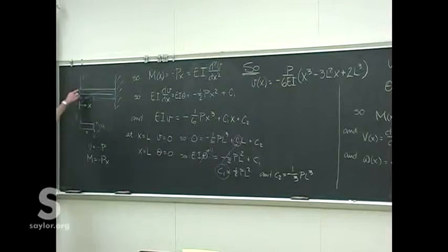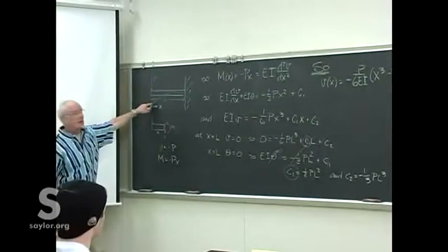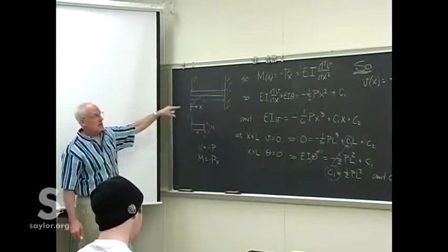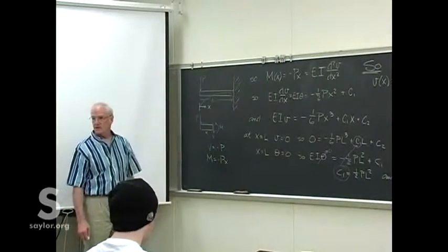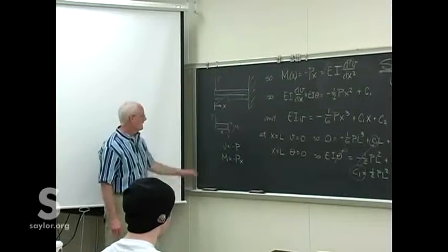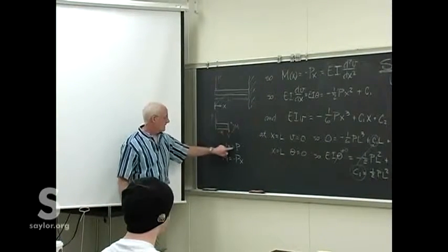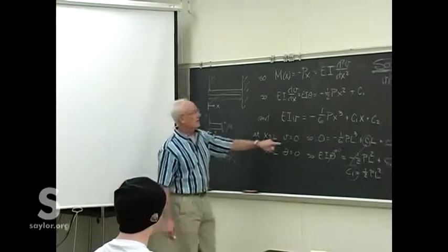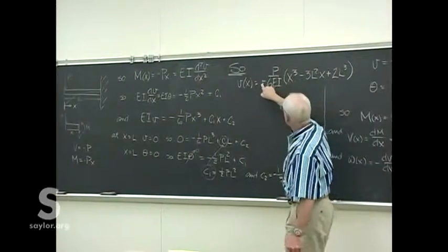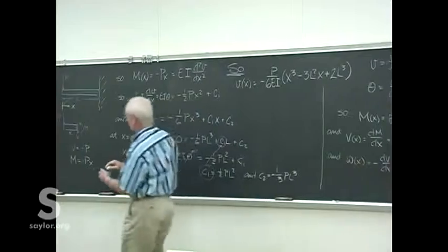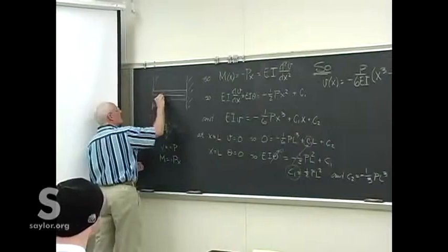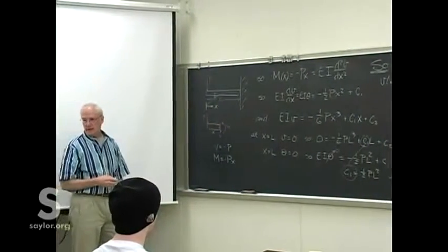So you've got a value for P, a length of the beam L, a material chosen E, and a cross section I. You can predict exactly where the beam's going to deflect. And with this kind of load, you always start by putting everything in the positive direction. Because if you do that, then you've got the minus sign that carries through. When we put in all these values, you'll get a negative number for this, which means that the deflection is that far below the neutral axis at that point. And that works in all cases.